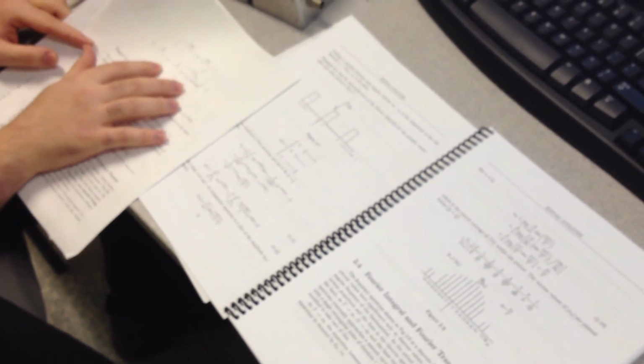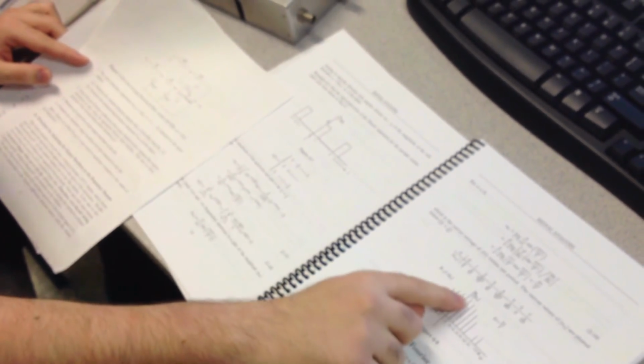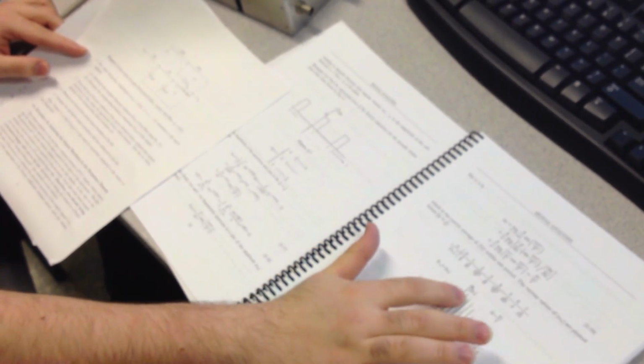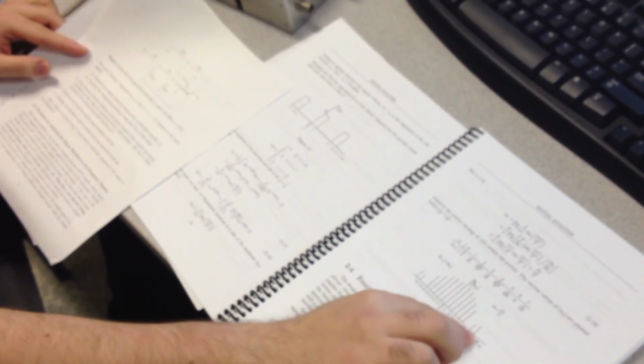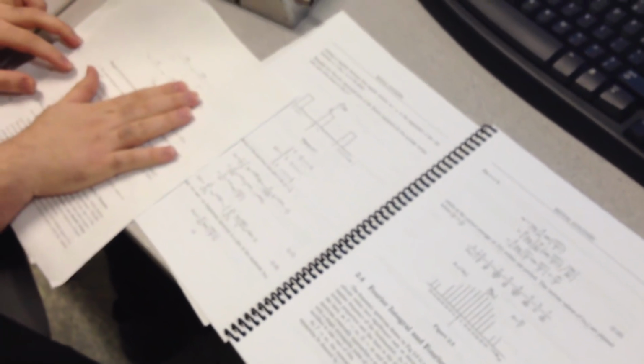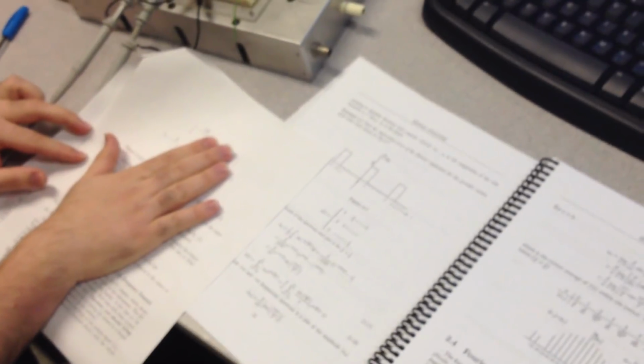When this signal is applied to this low pass filter, what will happen? The low frequency components may remain nearly the same, but higher order frequencies should be attenuated more and more. Since this is not an ideal filter but a real filter, it has no sharp cutoff.